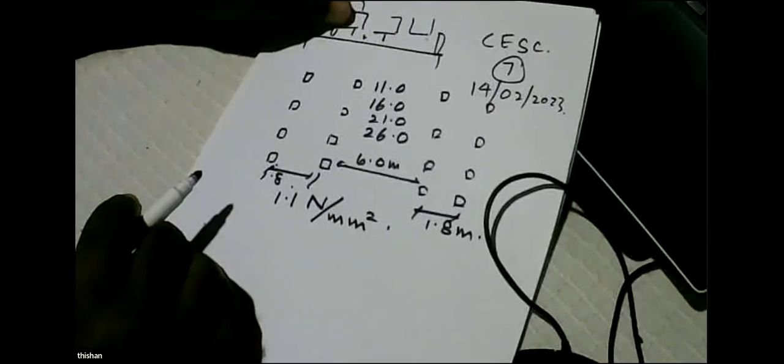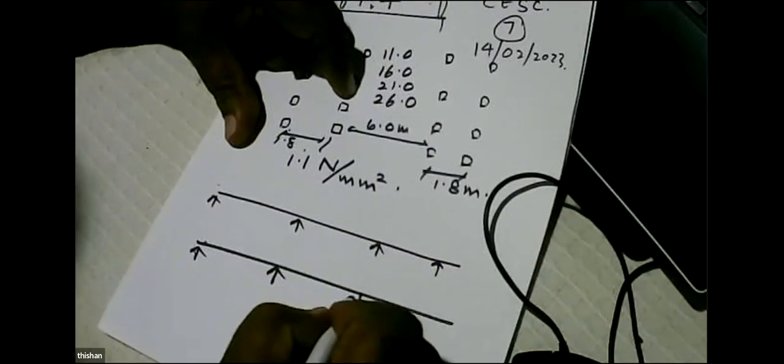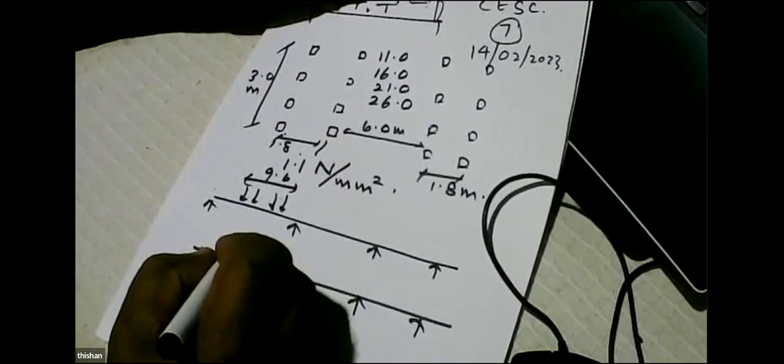And you will ask why? Why do we need vehicles of different length? In a continuous bridge like this, sometimes you'll find the bridge span is so large that we can place the whole 6 plus 3.6, 9.6 meter long bridge vehicle fully within one span. The span is large, and the width of the vehicle is 3 meters, but the overall width of the vehicle is 3.5 meters. So you might find this possible. On the other hand, you might find this is a different possibility.